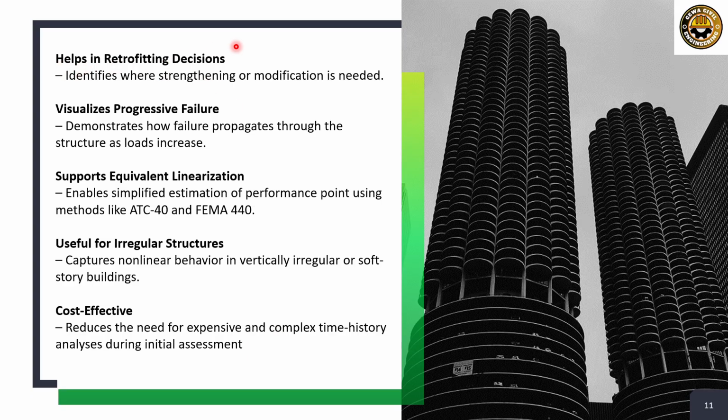The next and very important point, it helps in retrofitting decisions. I still remember that when I was studying pushover analysis for the first time, I was very astonished to know that we can analyze already designed buildings. For example, a building that is already designed and in service for a long time, and we still want to know whether it is able to withstand an earthquake, and what kind of seismic activity it can withstand.